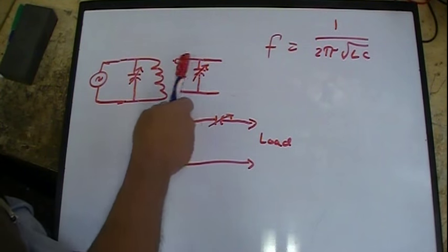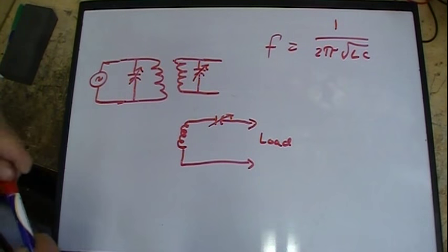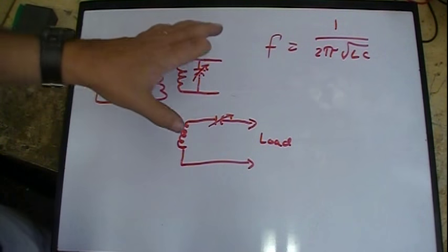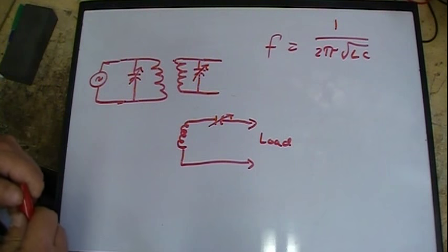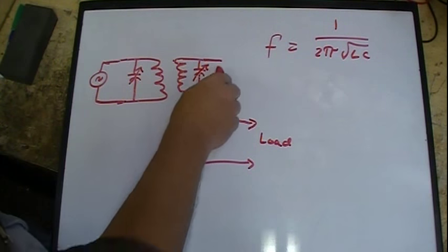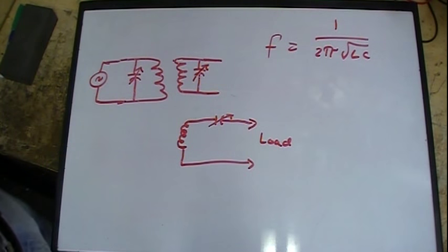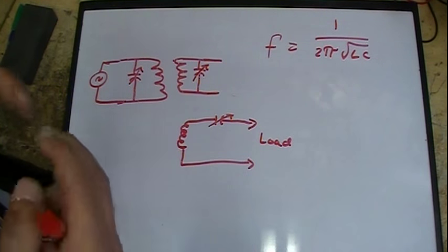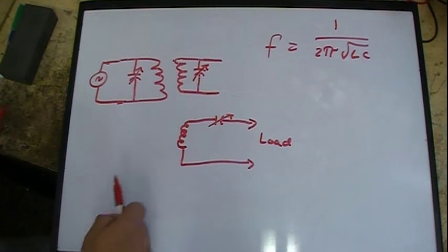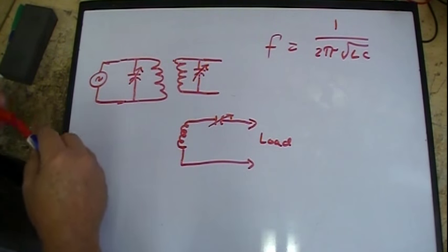We want this to be a little bit higher impedance to match out to the grid circuit, because this is going to tie to the grid of the IF amplifier tube. Grid circuits are high impedance. We like to keep those matched, so that the signal feeds in just fine.